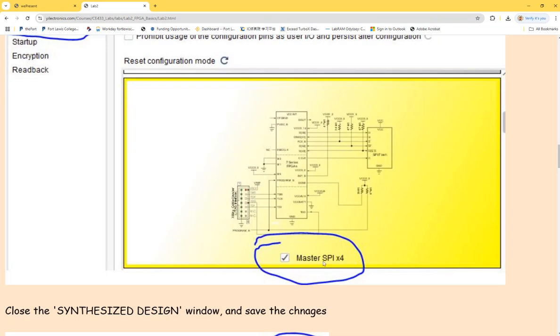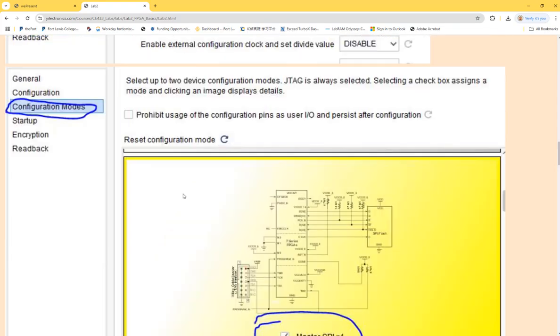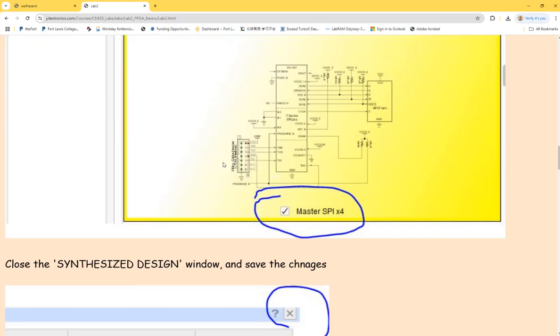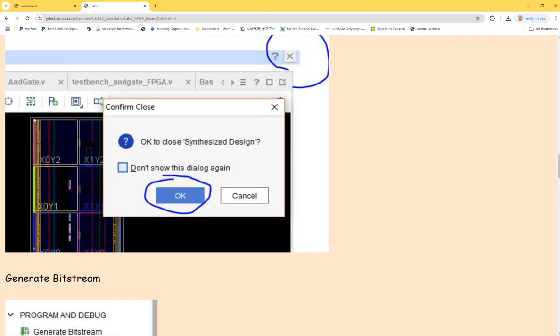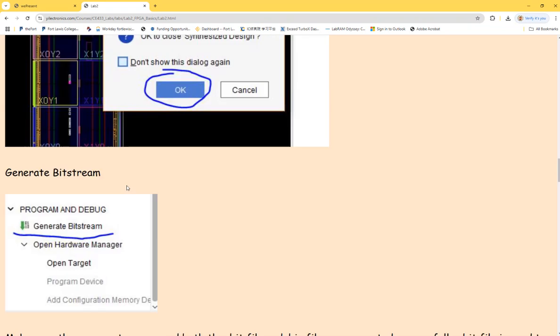So the communication between them is SPI. That's why during the configuration, you need to check this box. So select that port for the communication between the memory and the FPGA. So we are not really optimizing the design, but eventually all these digital blocks we don't really care about because it's so tiny. So you can skip, just click OK to skip this step.